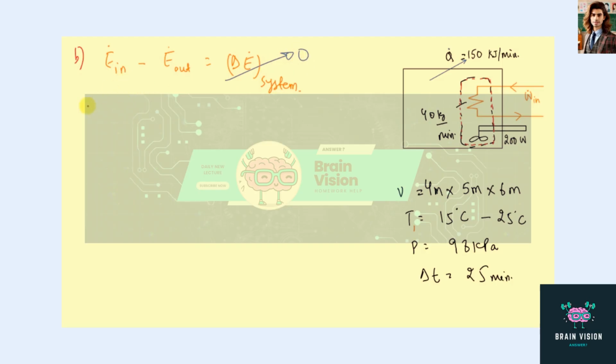Now energy in, we have the rate of work input by the electric heater plus the rate of work input by the fan, plus the initial enthalpy, that would be m dot h1, minus energy out, we have m dot h2, and it would be equal to 0.